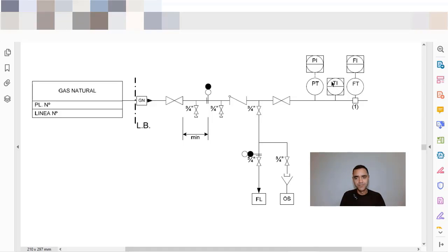We have the temperature and we have a flow transmitter. Depending on the kind of flow measurement being considered, for instance if you are using an orifice plate, in many cases we do the compensation. We use the pressure and temperature of the fluid in the operating conditions to compensate the information based on the standard conditions, like 0 Celsius degrees and 1 atm. So that is interesting to decrease the error that you can have associated with the operating conditions.